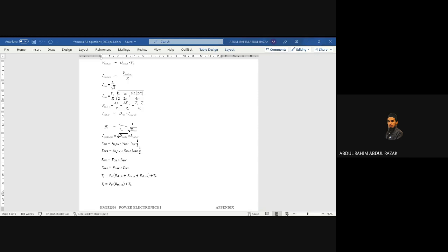So let's say we take any two parts as consideration. Actually, you may have to take into consideration up to 5 or 6 parts, skip some, choose the two best and propose one. So let's say we take a look at different manufacturers to see clearly how the comparison should be done. We take these two, this one from ST and this one from Vishay. Both have the same parameters, which can extend up to 29 ampere, 300 volt, but different manufacturers. So we put them side by side to compare the selected two.